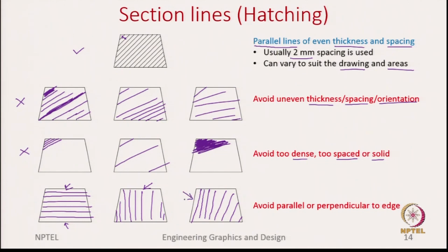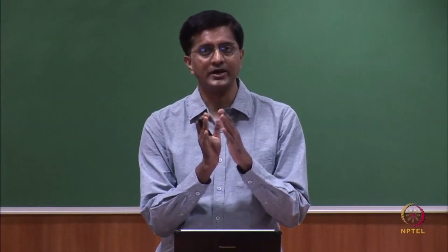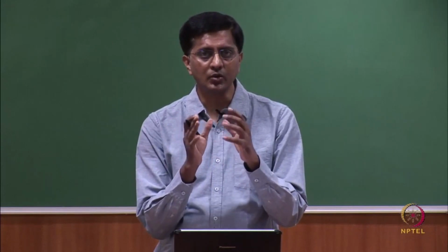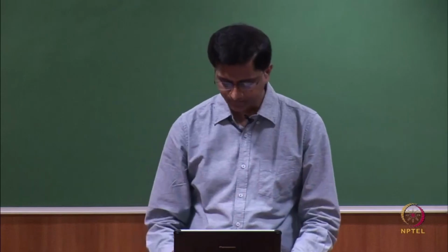So, now what is happening is these section lines are parallel to this edge, even this is poor practice. So, the best thing is you need to ensure that the section lines you are choosing are neither parallel nor perpendicular to any of the edges. Okay.